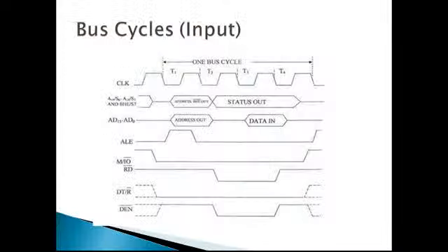Once you have an input device or an output device to be interfaced with the microprocessor, every such device needs to be given a unique address, a port address. In order to derive that selection logic, the port selection, we have to have some kind of address decoder. That is what we discussed in the last class. So let us continue discussion with that.